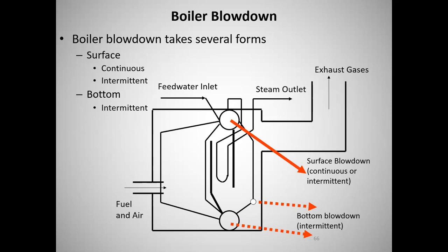So an easy way to measure the overall mineral content of the water is to measure the electrical conductivity of it. And so you can get a fairly inexpensive probe and system and sensors and all those sorts of things. And so you simply have a set point on your conductivity, and that sensor goes to an automatic valve, which is rocking back and forth, more or less open, to drain water out of the boiler to maintain your desired conductivity. Typical numbers I see, and what is this, micromhos per centimeter or something, 2,000 to 3,000, 3,200 is a typical set point on one of those sensors. And that's really the best you can do.